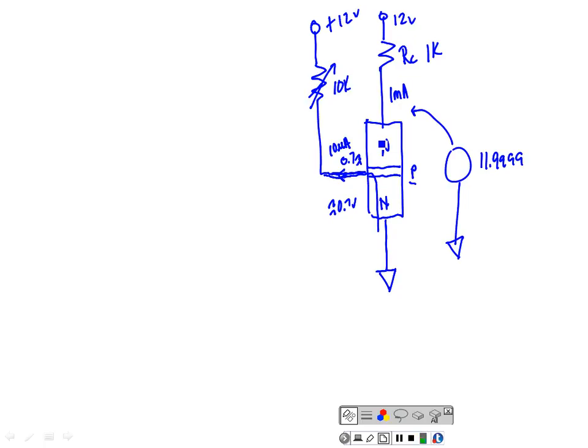You understand? These guys here give us a big current gain. It's just like last class when we was using those little old photo resistors and the little thermistors to control the speed of a DC motor. Well, a thermistor can't control the speed of a DC motor, but it can provide a little current that I can put into the base of a transistor, and the base of the transistor is going to give me a current gain, right? You understand?